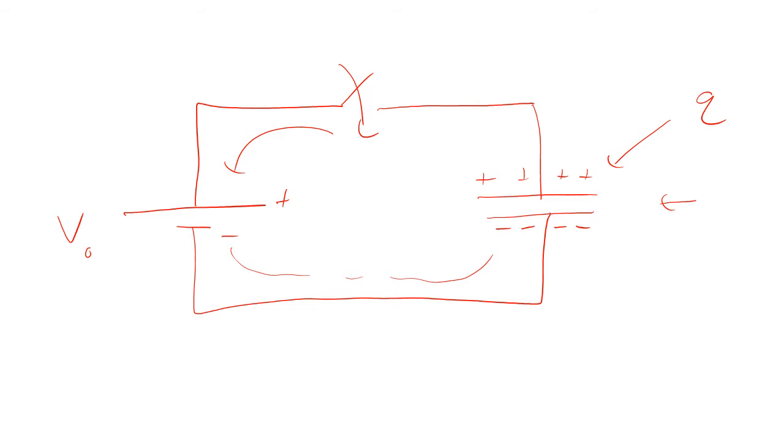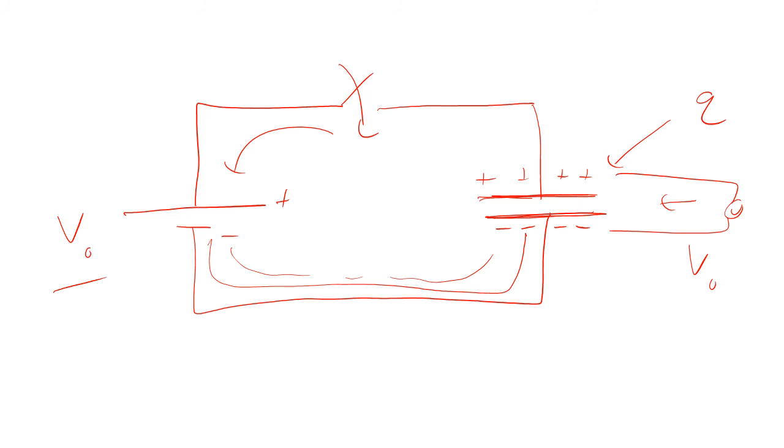And then the voltage on the capacitor is going to keep going until everything here, this is all a conductor. It's a wire, so this is all a conductor. We know that conductors are equipotentials. If there's a potential difference, then there's going to be an electric field there, and so current will flow until all of the conductor is the same voltage. So that means that if you were to take a voltmeter, a device that measures voltage, this voltage would equal the other voltage that we supplied over there. So that's how you connect a capacitor into a circuit.